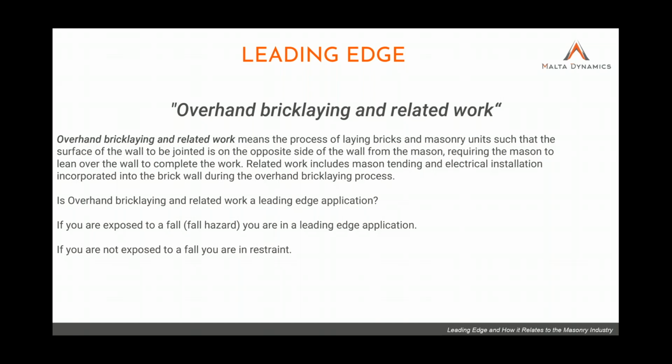Is overhand bricklaying and related work a leading edge application? Yes, most of the time it is. The only time you can get out of leading edge is if you're putting the worker in restraint, or if you're making sure that that anchor is above their head. If you're exposed to a fall, you are in a leading edge application. If you're not exposed to a fall, you are in restraint. Remember restraint, it's one of the key solutions.